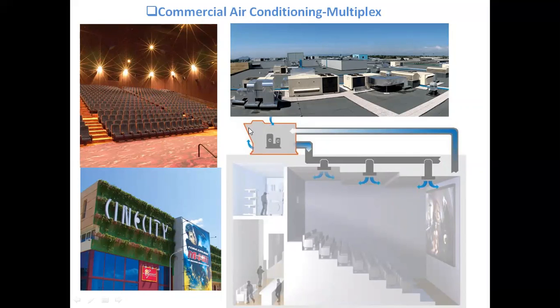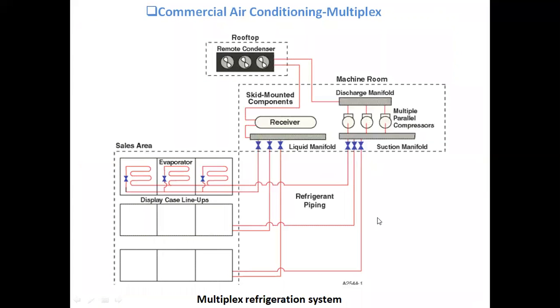it works. The AHU and the chiller room, as I discussed in the previous slide, are here, and the air which comes here, as shown by the red arrow, comes out here and is distributed evenly in the room so that the air temperature is maintained. Part of the air, as I told you, is returned back to the AHU, and most of the air is exhausted because lots of human beings are present in the room. So in order to supply fresh oxygen, fresh air is mixed in this room, right? So one of the commercial applications is shown.